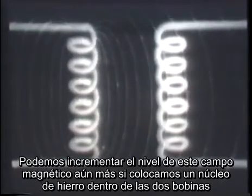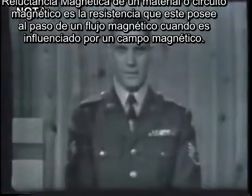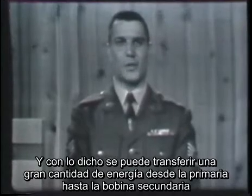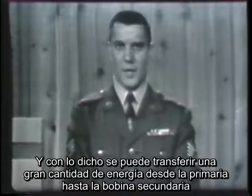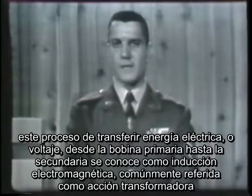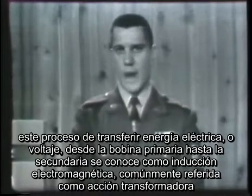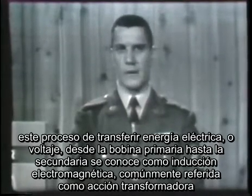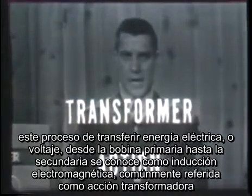We can increase the strength of this magnetic field even further if we place an iron core inside the two coils. Now all the magnetic field will travel inside the iron core because it offers less reluctance than the air around it. Now this in turn permits a greater amount of energy to be transferred from the primary to the secondary coil. This process of transferring electrical energy, or voltage we might say, from the primary coil to the secondary coil through electromagnetic induction is commonly referred to as transformer action.